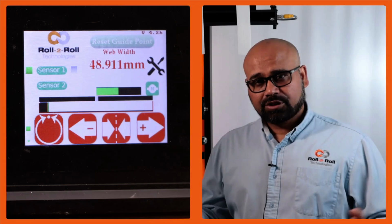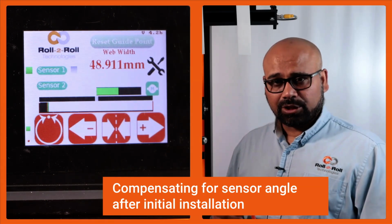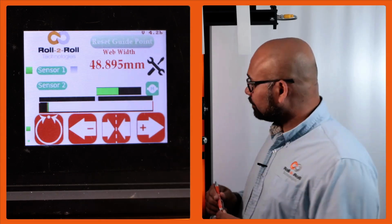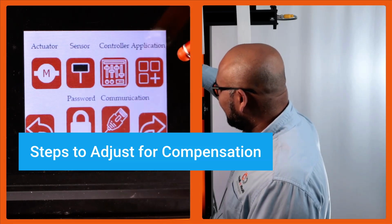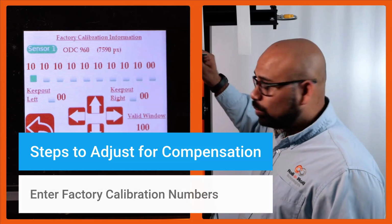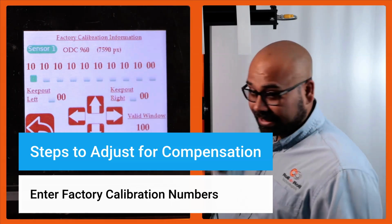When you first install the system and you want to compensate for the angle, the way to do that is to go into the power user screen, and from there you can set this up. To get there, click on the tools icon, bottom right, power user, and then go into the sensor. You can see sensor 1, and it's identifying as ODC960. This is the number of pixels it has and all those kinds of things.